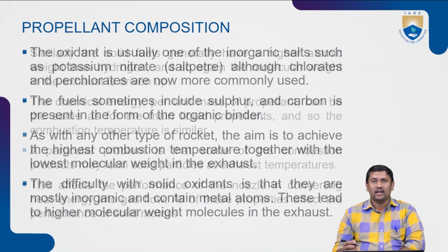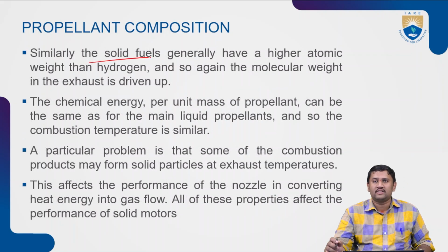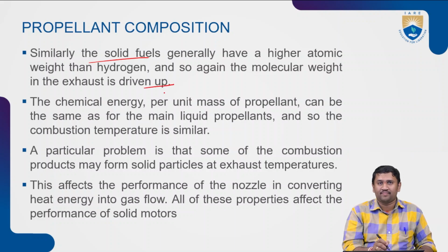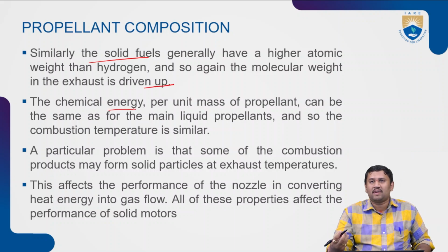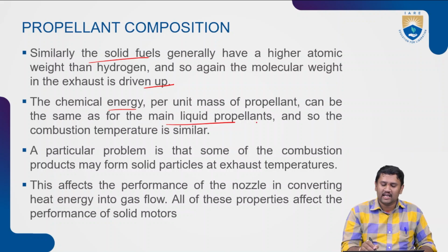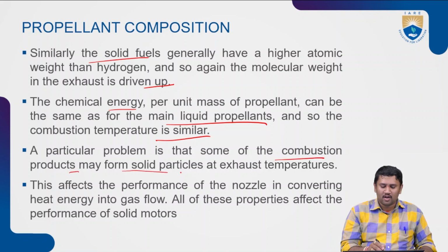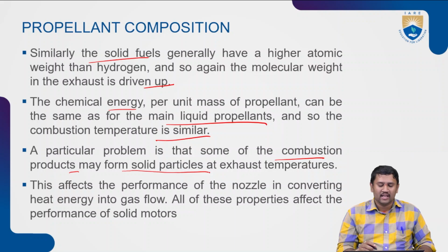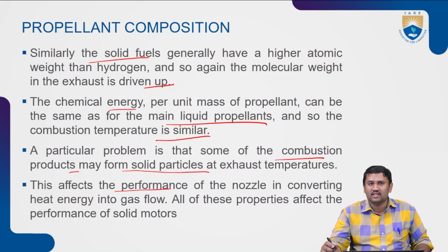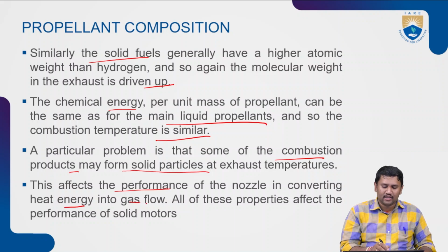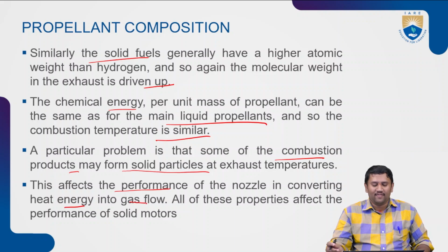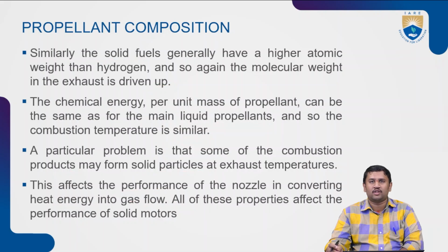So similarly, the solid fuels generally have a higher atomic weight than hydrogen. So again, the molecular weight in the exhaust is driven up. The chemical energy per unit mass of propellant can be the same as for the main liquid propellants, so the combustion temperature is similar. But a particular problem is that some of the combustion products may form solid particles at exhaust temperature. And again, this affects the performance of the nozzle in converting heat energy into gas flow. All of these properties affect the performance of solid motors.